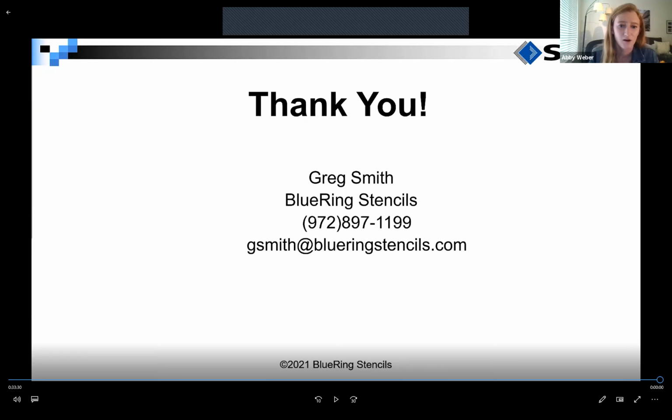Great. Are there any special aperture designs to follow when using a closed print head? So when you're using the enclosed print heads, it does kind of change the rules with step stencils. The question earlier, there's a step on the top, on the squeegee side or contact side. So there have been cases with customers with an enclosed print head where we've had to put the steps on the bottom side of the stencil.